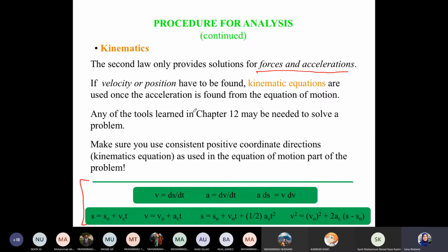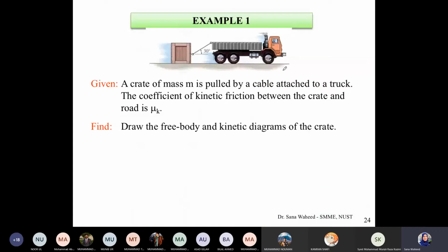So all of that we still need to carry with us, that baggage, because of the interplay between kinematics and then jumping to, okay, if this velocity profile is given, then what force would be needed to cause it. So first we'll have to use kinematic analysis to go from the velocity to the acceleration, then use kinetics to go from acceleration to the forces. Perfect. So with that, I'm going to take a break and then we'll come back to do some examples for kinetics, basically in the XY coordinate system.